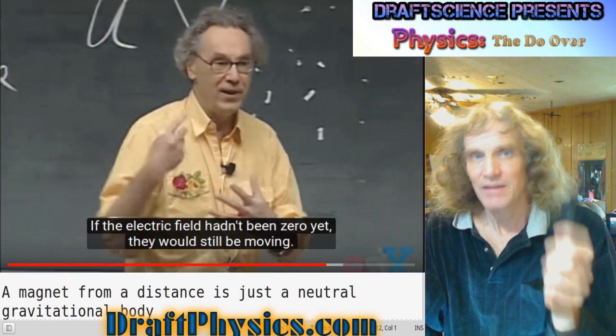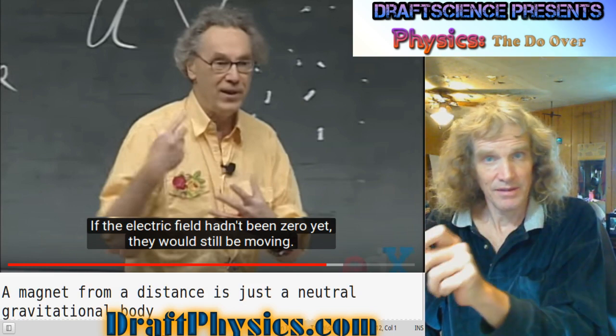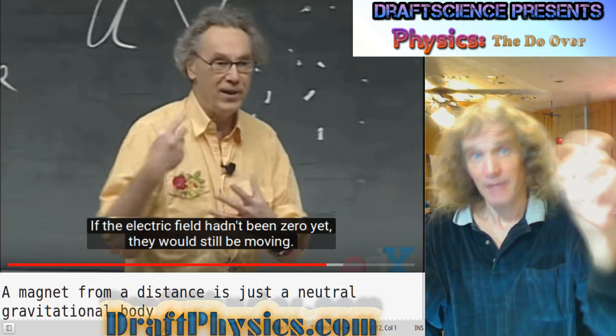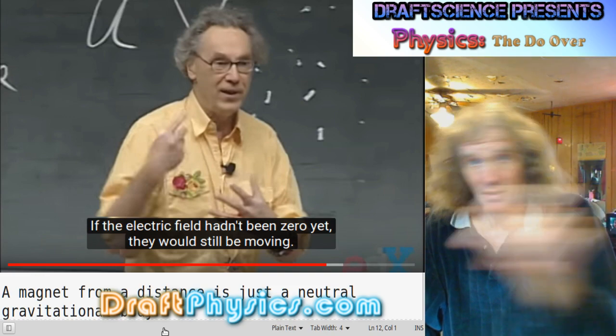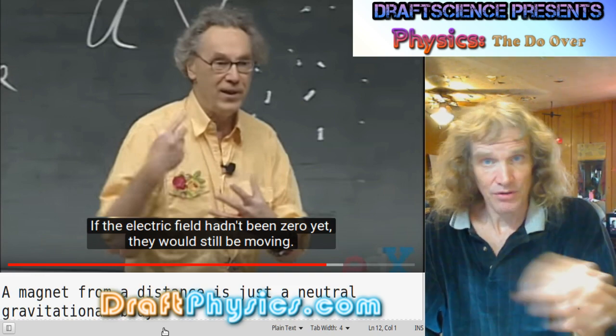All right, they don't kill any electric field. They kill any difference in their electrical potential. So they wipe out any difference. They can still be 90,000 volts, but it won't be 100,000 over here and 0 volts over here. They get rid of the linearity. Everything becomes one voltage potential.